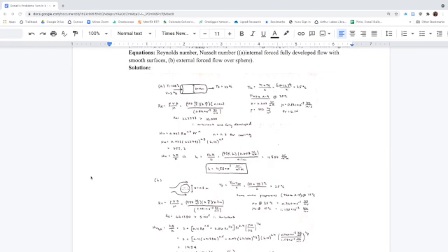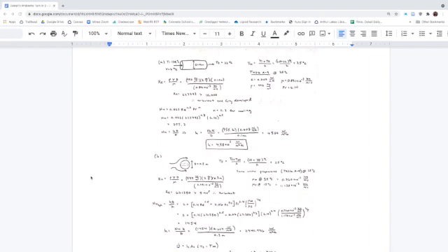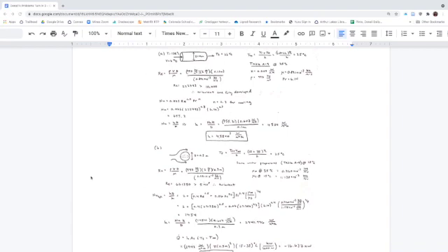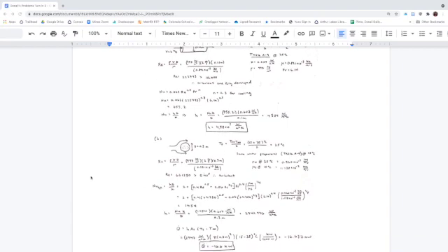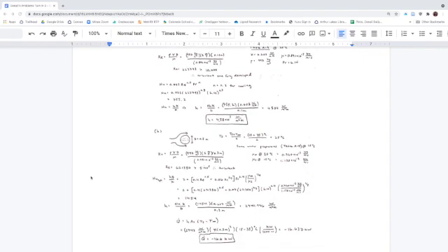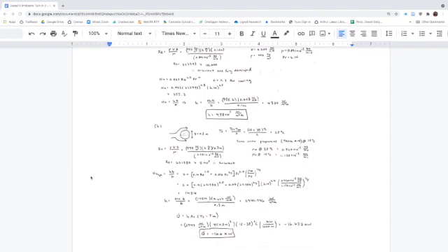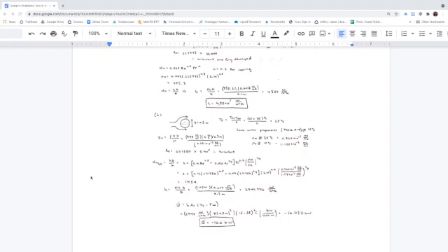In Part B, water is forced to flow over a spherical rock, so this problem covers learning outcomes 5C, spherical coordinates, and 7B, external forced convection. Properties are found at the film temperature, while mu infinity and mu surface are found at their respective temperatures. Using the appropriate Nusselt number equation for flow over a sphere, the convective heat transfer coefficient can then be calculated. From there, the heat transfer rate can be found. Here, Q equals negative 16.6 kilowatts, so the heat transfer rate is away from the rock.